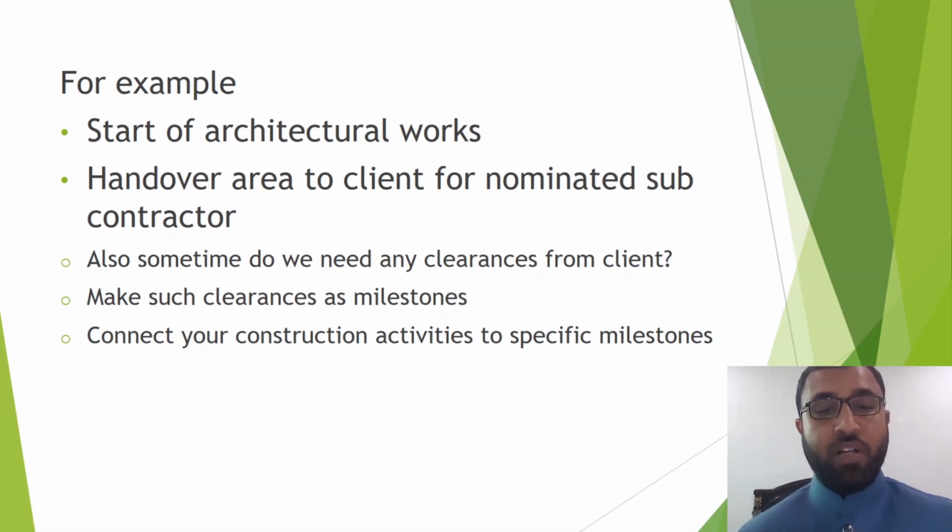Also, sometimes we need clearances from the client. Make such clearances milestones. Connect your construction activities to specific milestones. Sometimes we need clearances from the client when they are going to hand over some area to us, when they are going to deliver some material to us, and when they are going to release some project information. We don't know the duration for that activity, so just make that activity a milestone. Maybe that is not a contractual milestone, but still they have agreed. If they have agreed through a letter or the minutes of meeting, then you need to include it in your schedule.